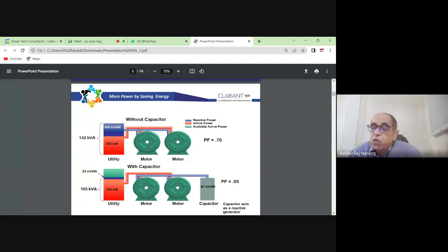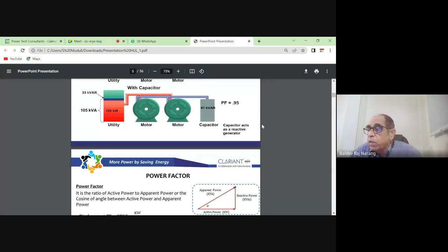So the harmonics also play a role in getting the true power factor. And normally, so far, the utilities have been taking care of only the displacement power factor, and the harmonics one by one they are incorporating in the meters, so that the meters are capable of accounting for the total harmonic distortion and record the true power factor. But ultimately, it is going to come.